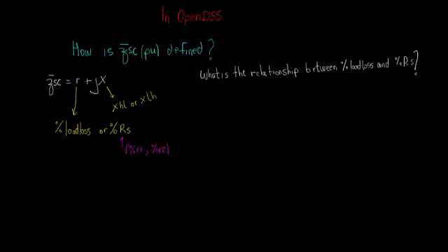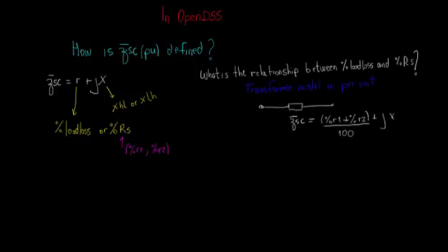What is the relation between %loadloss and the transformer series resistance? Neglecting the transformer magnetizing branch, its model in per unit is essentially a series impedance called ZSC. The total series resistance of the transformer is %R1 plus %R2, and XHL represents the impedance measured from the high to low side of the transformer, or between the high-low pair of windings.